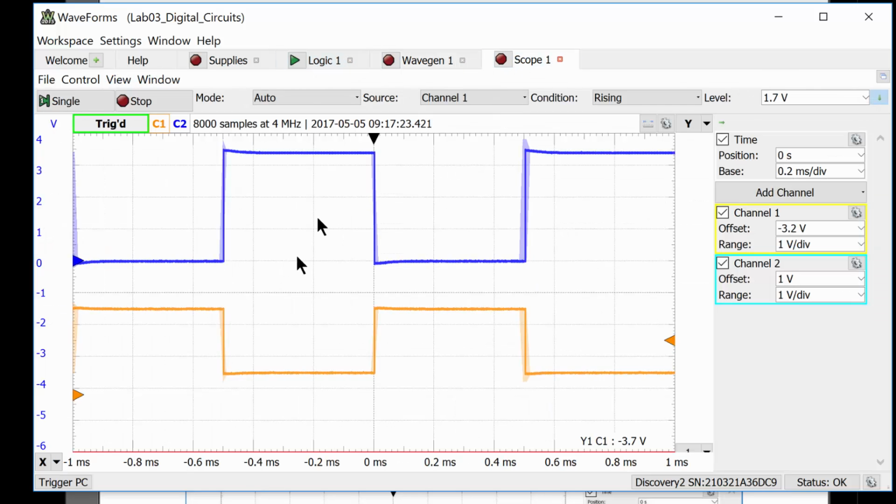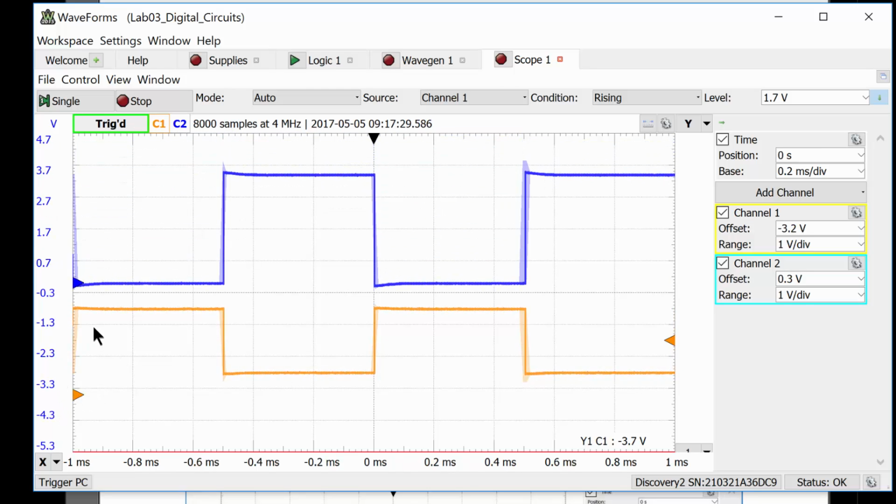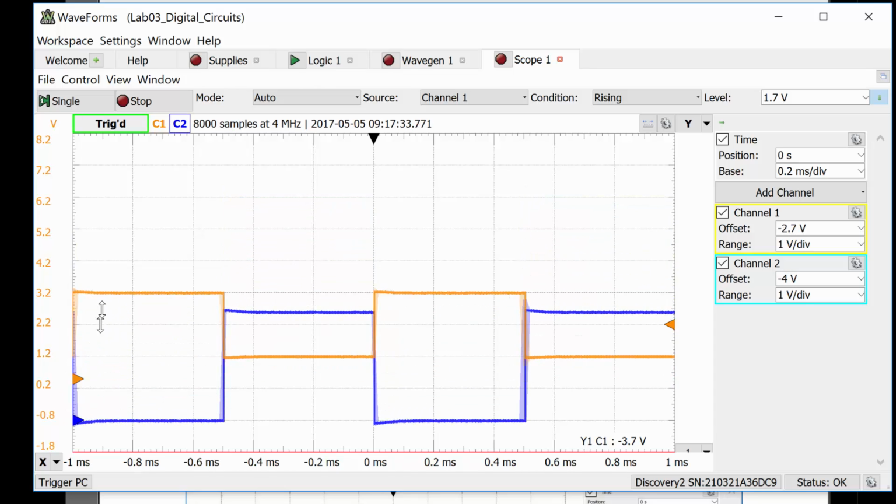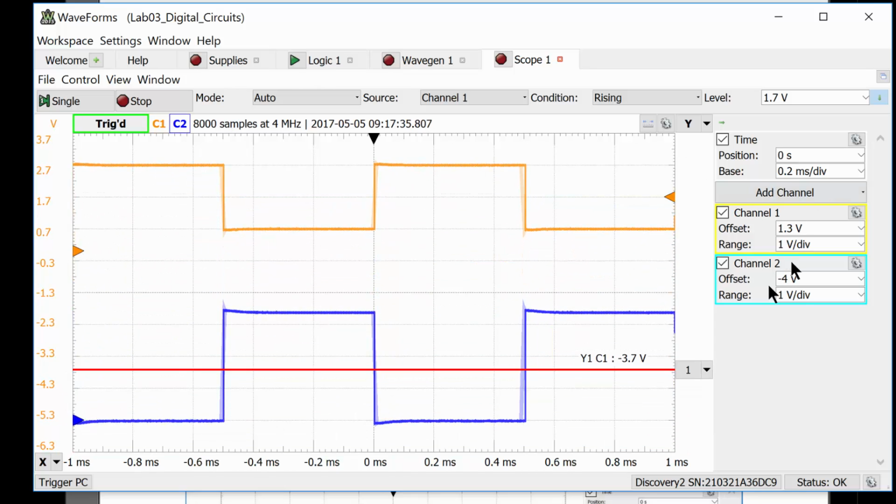and then go back to the oscilloscope, look at what happened here. Oh, I'm sorry. This is the input down here. So let's put the output on the bottom and the input on the top. And notice now, since they're on the same scale, these are representative of what they actually look like relative to each other. This is actually getting pretty small. But notice that the output is still working very well. So it means that the input can shrink quite a bit before the output starts messing up.